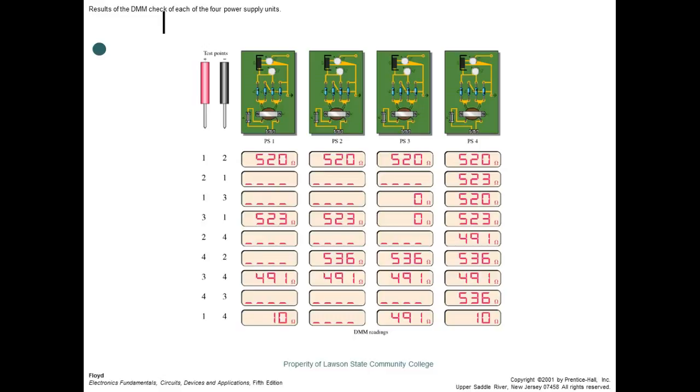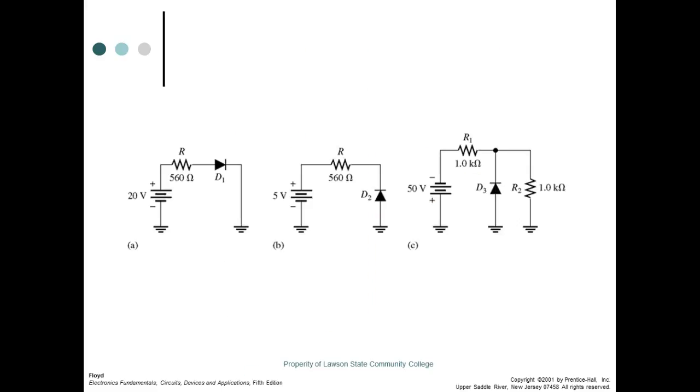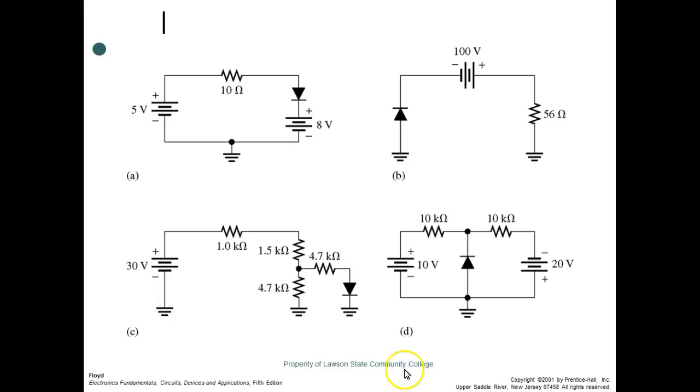So before you put an ohm meter in a circuit, first thing you should do is put it on volts and check to see if there's a voltage there, because you could damage your meter. It could damage you too if the meter blows up. Just a few little safety procedures. It doesn't make any difference how many years of experience you've got, right? Okay.